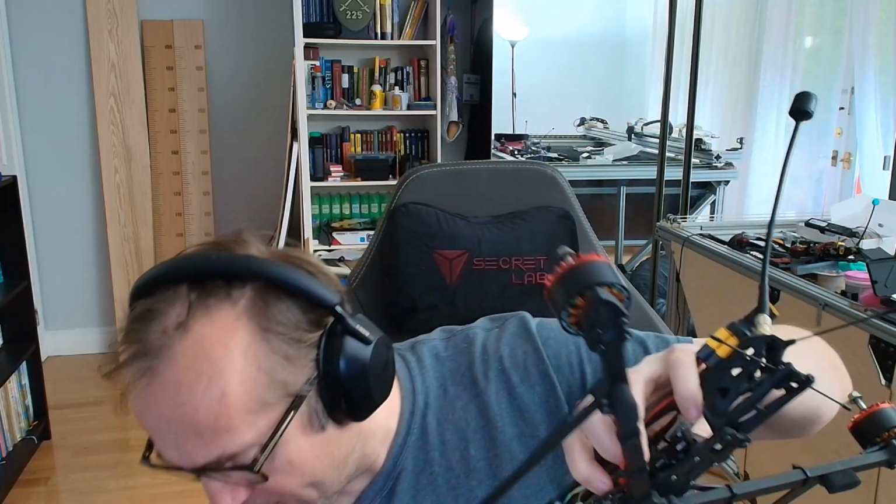So let's start. The first thing that we need to do is connect this drone to the computer. But since we are going to modify the firmware, we need to move this drone into DFU mode. There is a button on the Matek. Where is my USB-C cable? I have to push this button and hold it, and after that connect my Matek to the computer. Done. And now it's connected to the computer in DFU mode, so I can start flashing it.